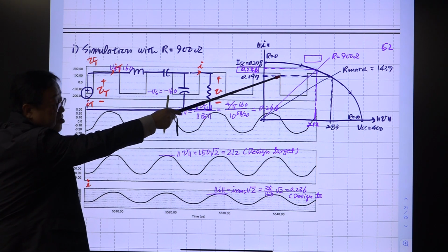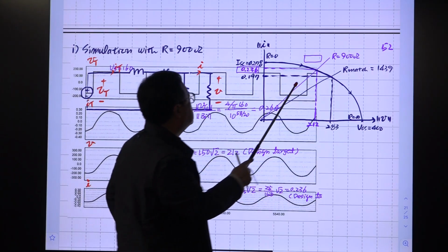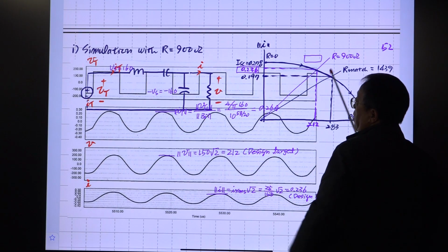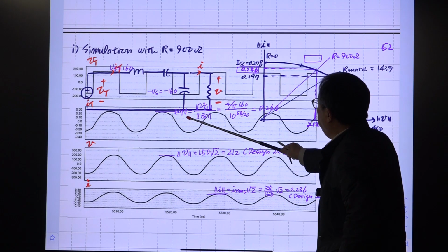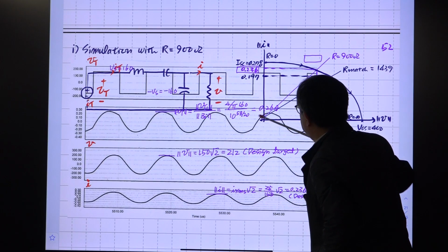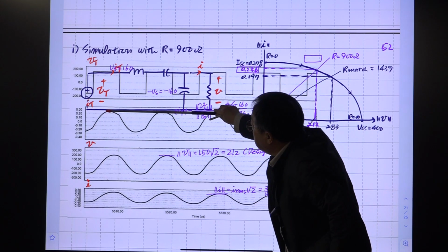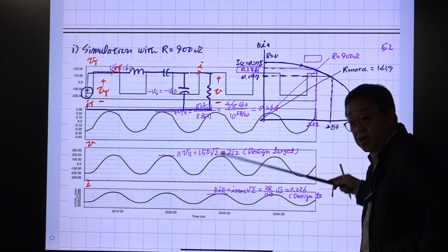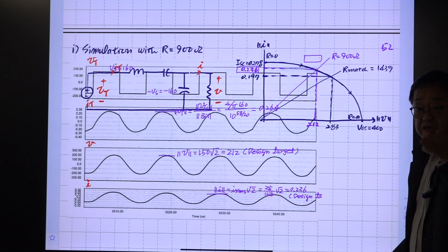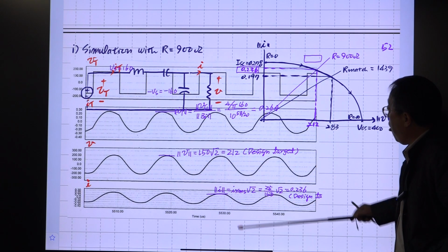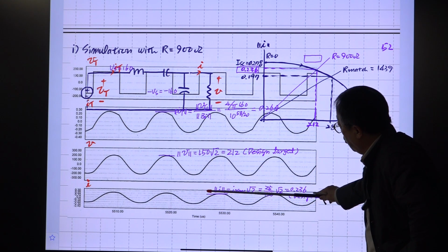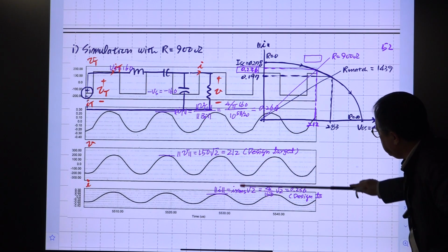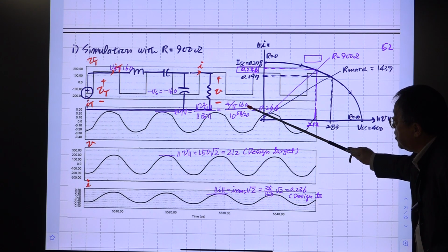So this is the operational point. The operational point is here. This is the maximum power transfer point, and everything matches. This is the prediction of IT, and the magnitude of this one is 0.26. This value is very close to 0.26. This is different from sinusoidal waveforms, but the peak values match very closely, right? The same is true for our output voltage and this load current, load voltage. This value is very similar to the design target, or your prediction, okay?